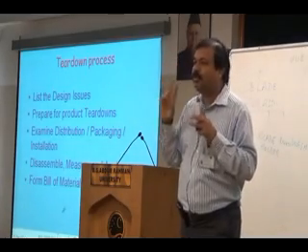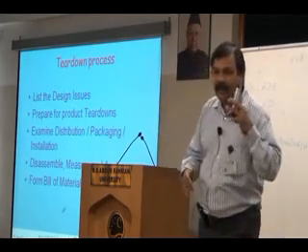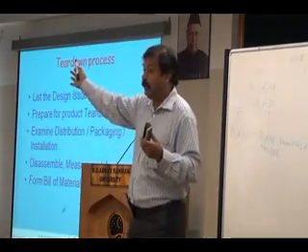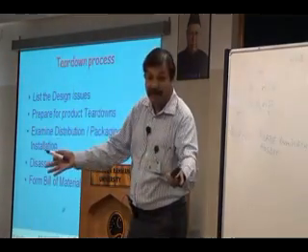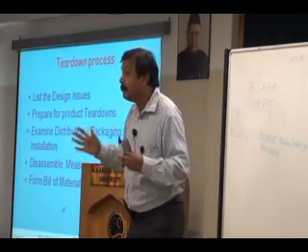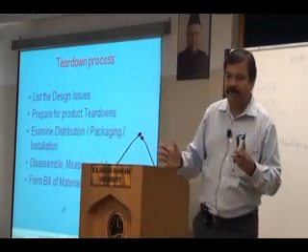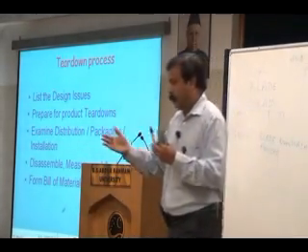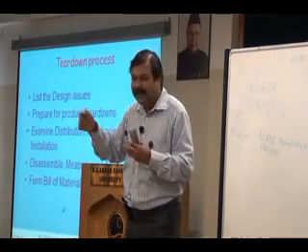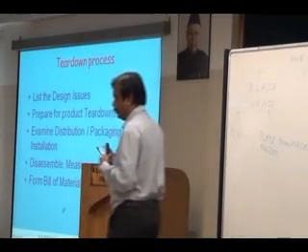So there are only 2 options. One is called spot welding, which is very difficult. The other one is riveting. In all the bus body construction, the skin of the bus is attached to the frame by, what is the process? It is by a riveting process. So again the same issue. You have a very thick frame and a very thin skin, they are joined together. Riveting is the ideal process.